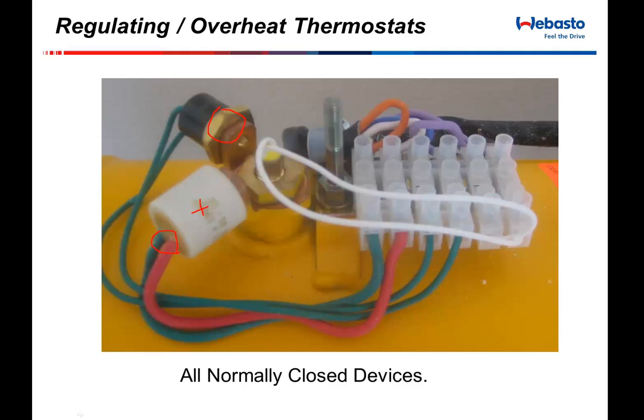You've got 2 common reasons why you would be overheating the Webasto. The first is that if you've got a valve shut down in the system, the driver turns the heater on, the Webasto will start operating, but it's only heating the water inside of itself, and it will do that very, very rapidly. I mentioned before that at 0 degrees this thing will run for about 30 to 35 minutes. If you're finding that the thing is only running for 3 or 4 minutes at a time,